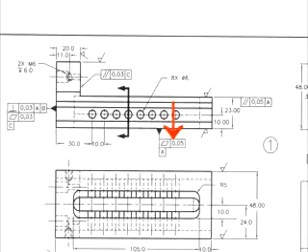If we look over here now, we can see that the bottom surface of this front view has to be flat within 0.05 of a millimeter, and that this bottom surface is also datum or reference surface A. And if we look here, we can see that this surface needs to be parallel within 5/100ths of a millimeter to that datum surface A. And finally, for this view, this vertical surface needs to be parallel to within 3/100ths of a millimeter to datum or reference surface C.